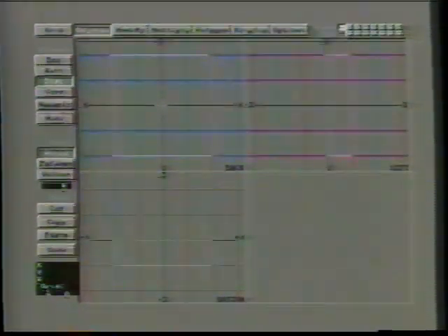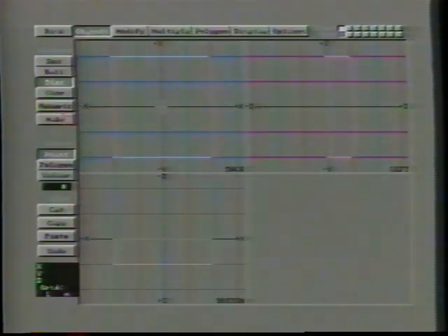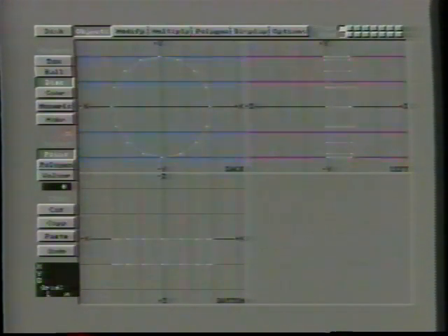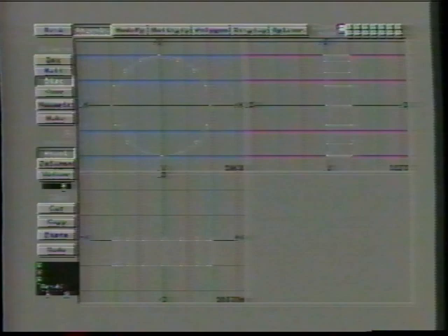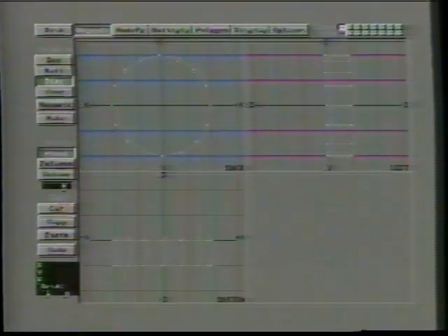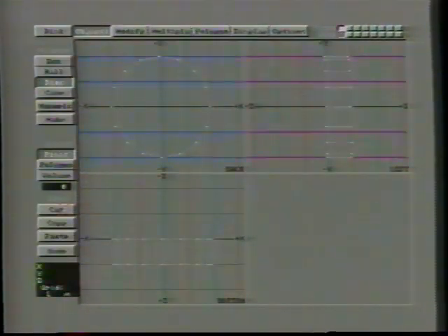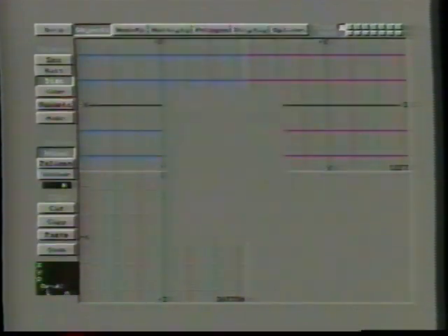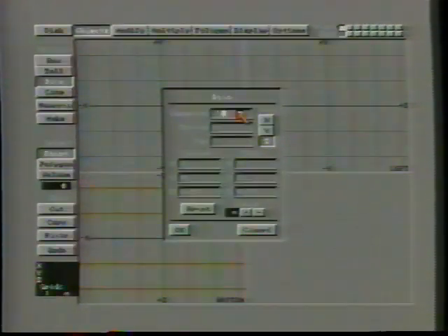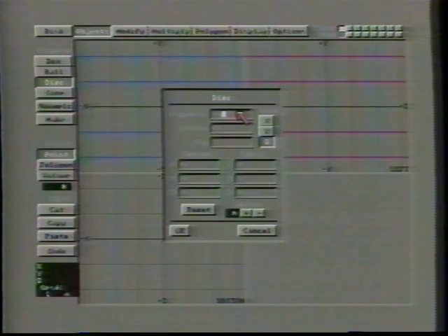When I'm satisfied that I have everything right, I click on the Make button, and that makes my disk. One thing to point out here is that we're using 16 points to make up our circle. Now that's fine for most applications, but this needed to be really nice. So I went into the numeric function and took out 16 under segments and put in 64.